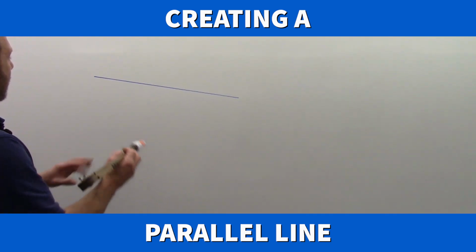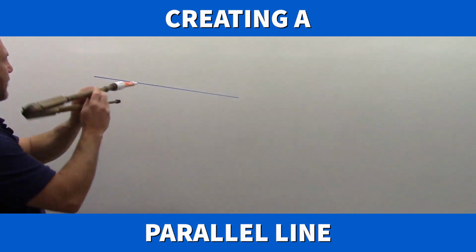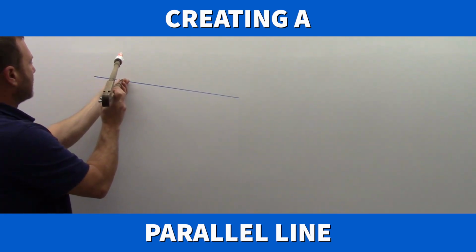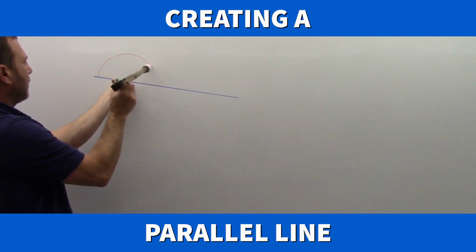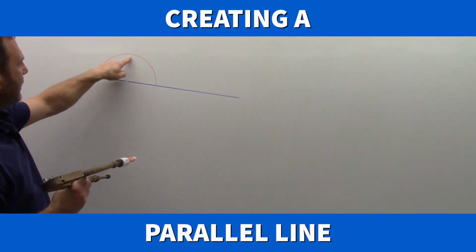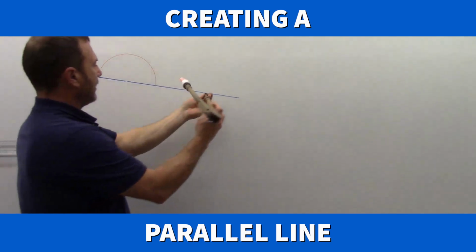Now what I'm going to do if I have a required distance for the parallel line, that's what I'm going to set my dividers to. So if I need them 2 inches apart, I set my compass to 2 inches. And I'm going to set it on the line, and I'm going to draw an arc. So now I know that the radius, the very peak of this arc, is 2 inches away from my original line, and I'm going to do that twice.